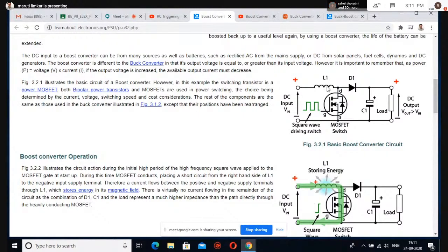Here, the voltage across the inductor is such that its polarity is left hand side negative, right side positive, and its magnitude is L di by dt. So this plus this voltage, the capacitor will charge up to this plus this voltage. Means ideally this is Vs, VDC. Inductor will be charged up to VDC.